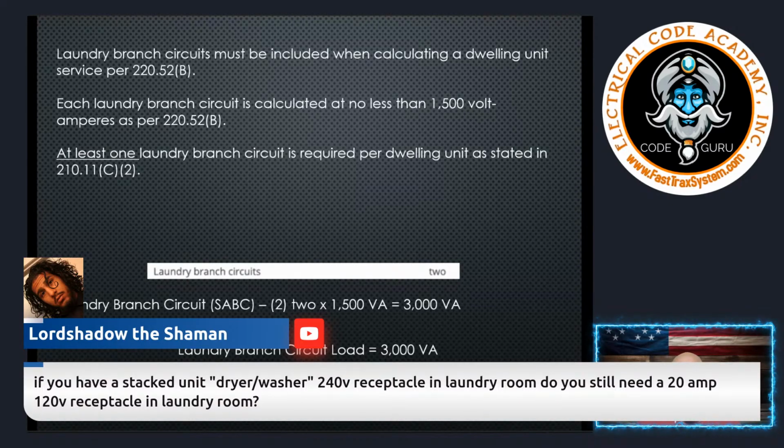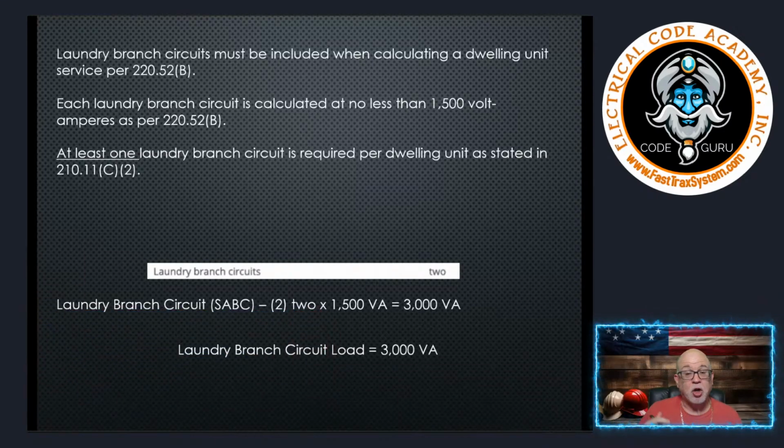There is nothing in the NEC that requires a dryer circuit, a 30 amp dryer circuit. Now, obviously, if you're on an exam and they give you a dryer, then you have to take that into consideration because they gave you the value. In fact, we do today on ours. But you're not required to put a dryer in, or to calculate for a dryer unless, of course, it's being used. And if it is, then you have to apply it.